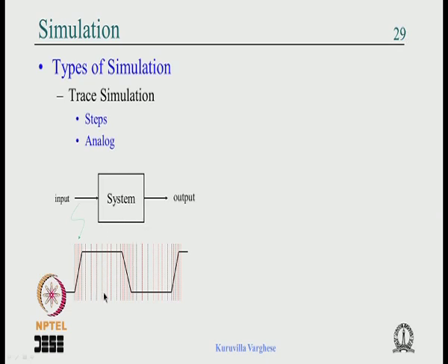But you know that in a SPICE simulation it is going to divide the whole period into minute intervals. It need not be uniform, because in a trapezoidal waveform the maximum information is in the slopes. All the harmonics, the frequency content, come because of this rate of change. So there will be a lot of divisions, a lot of steps there. When it is stable, maybe fewer steps.